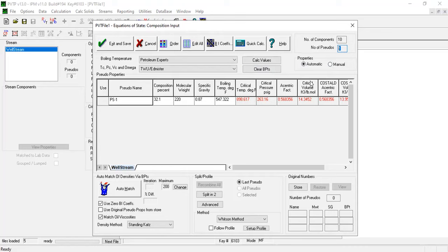Okay, why do so? So this is our first milestone. We have inputted the pure components and also the pseudo component, and we also get the physical or thermodynamic properties of the pseudo component. So this is our first milestone, and we want to preserve that, so that when a characterization strategy does not yield a desired outcome, we can go back to the previous milestone.